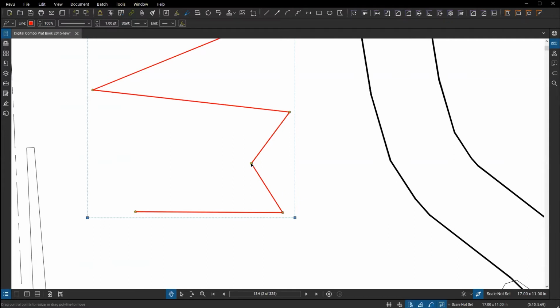A faster means of doing that is with our friend shift that we've used a half dozen times already. Just shift, pick, and wherever you pick, you see a new control point show up there. And then I can manipulate that path however I need to by adjusting that control point location, left clicking and dragging to change where that path is supposed to go.